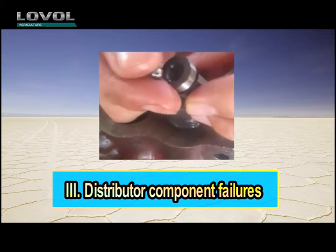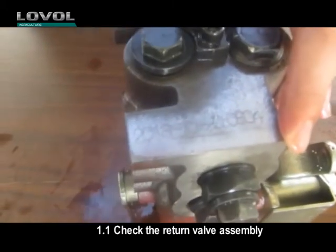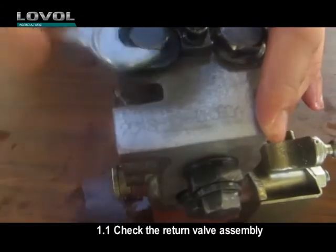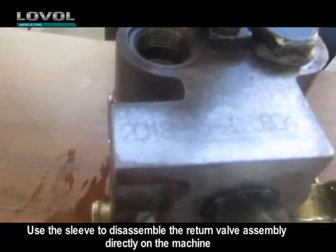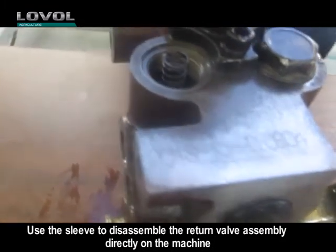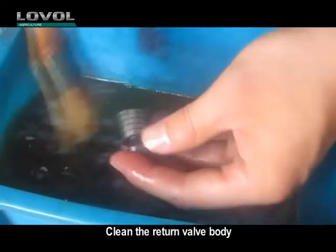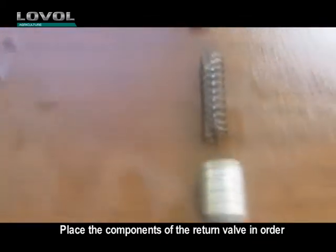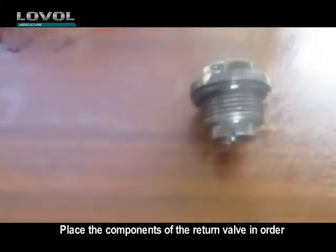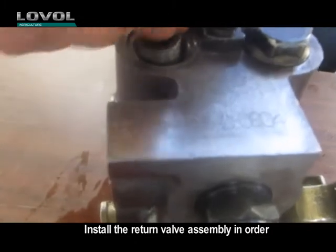3. Distributor component failures. 1.1 Check the return valve assembly. Use the sleeve to disassemble the return valve assembly directly on the machine. Clean the return valve body. Place the components of the return valve in order. Install the return valve assembly in order.